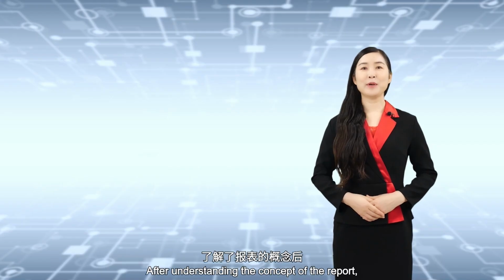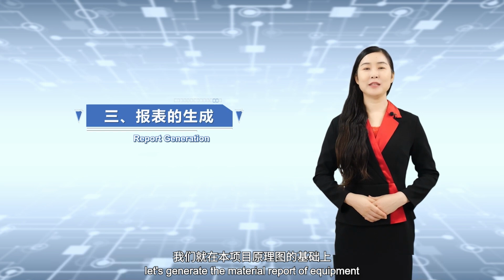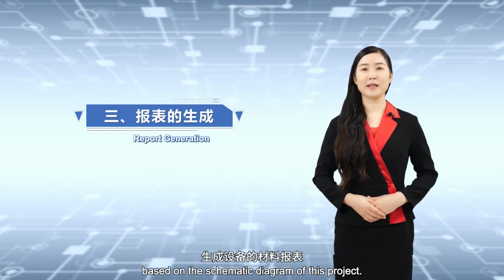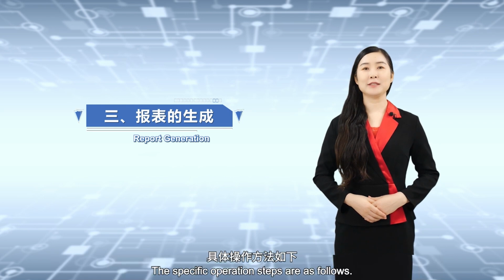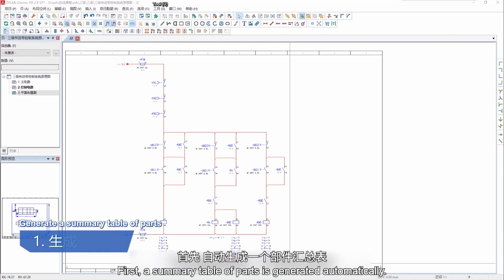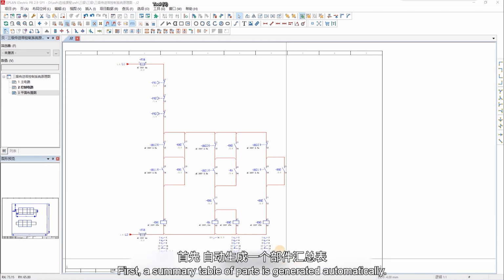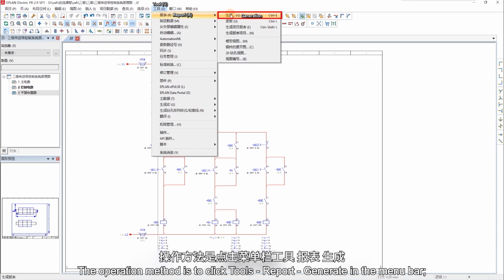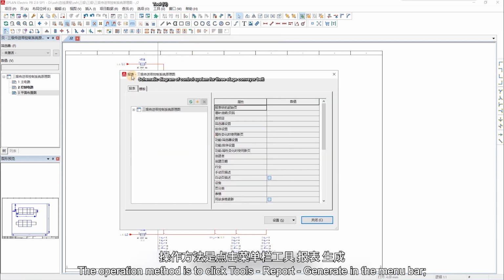After understanding the concept of the report, let's generate the material report of equipment based on the schematic diagram of this project. The specific operation steps are as follows. First, a summary table of parts is generated automatically. The operation method is to click Tools, Report, Generate in the menu bar.